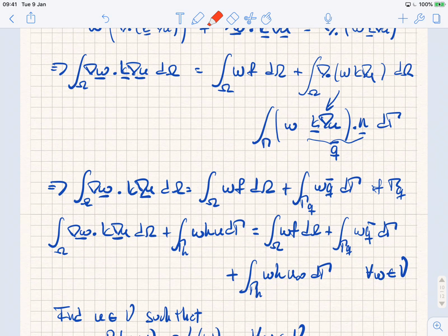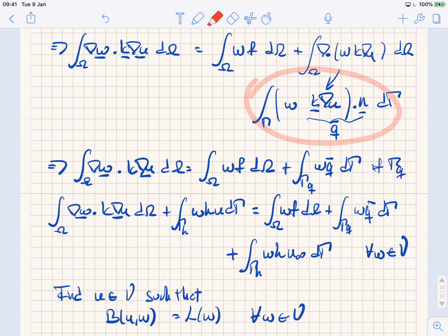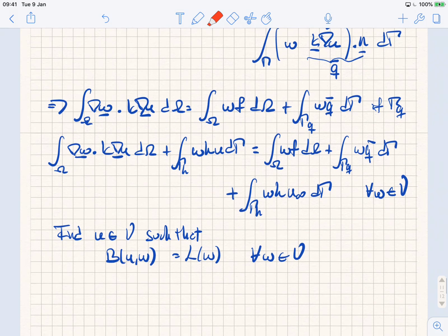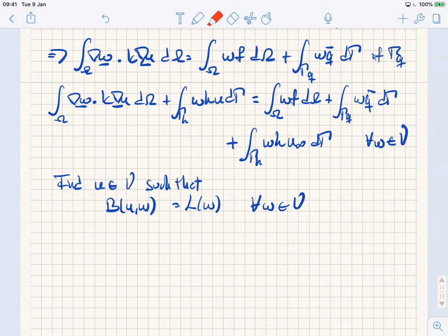and that was it. The only thing that we do after obtaining this term is just replacing by the boundary condition. So if you are dealing with a problem that has only a Neumann boundary condition, what you get is this expression here. You see there is no gamma h there, only Neumann type of boundary condition. But if you have a convective boundary condition, then your formulation gets a little bit more complicated. So it has 2 additional terms that are showing up from the 2 terms that define the convective boundary condition. And that's it. That's basically the heat conduction in 3D.